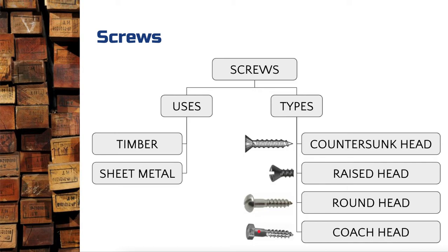If I'm thinking of where I've used these in my own applications, coach head screws, I've used them quite often when mounting TVs to the wall. Because of the fact that I can use a socket set on them, it means that it's really easy to drive in, and I would actually be driving it into the timber stud wall. Okay, so that's why that really deep thread there, and really enormous gripping power.